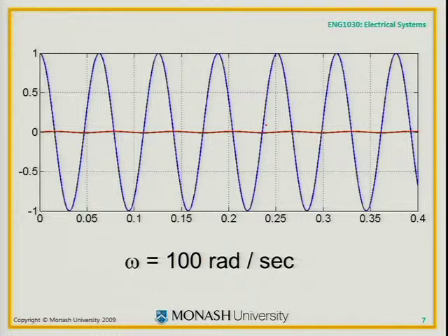So the answer was decreases. And why does it happen? Well, at low frequencies, an inductor looks like a short circuit. We see, in fact, at DC, it looks like it is a short circuit. But that means at low frequencies, like 1 radian per second, it essentially is a short circuit. Okay? It's really not doing much.